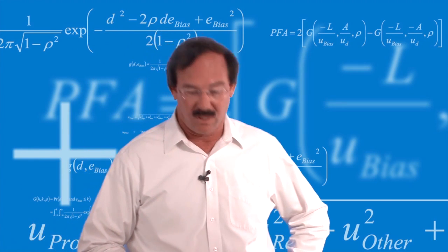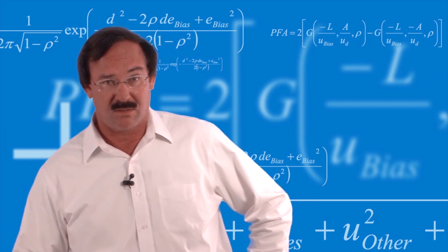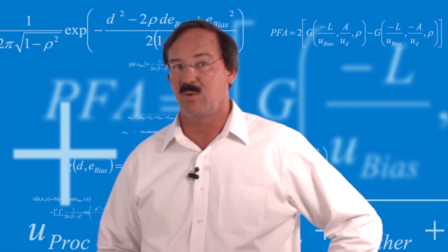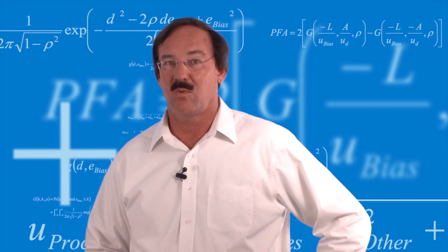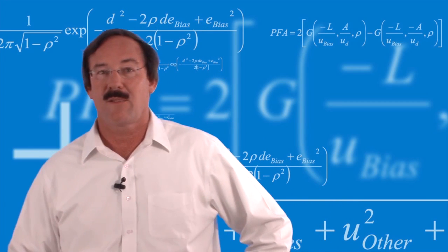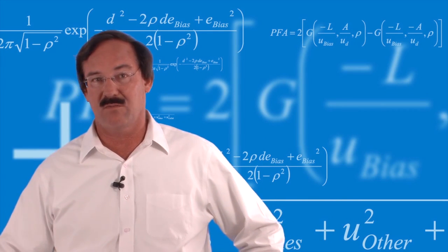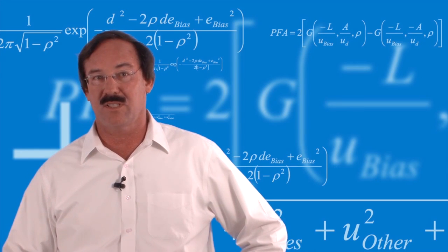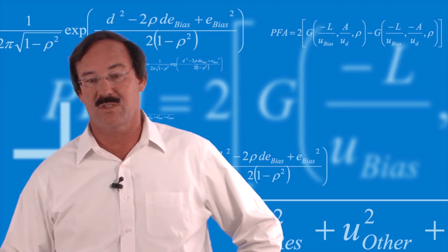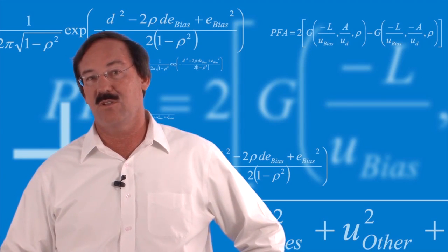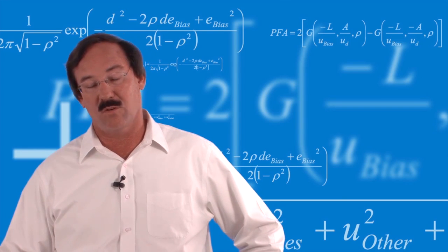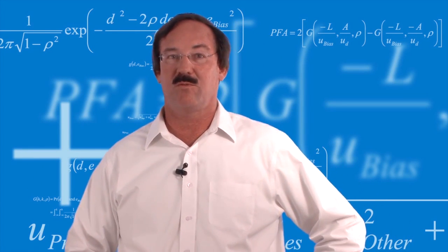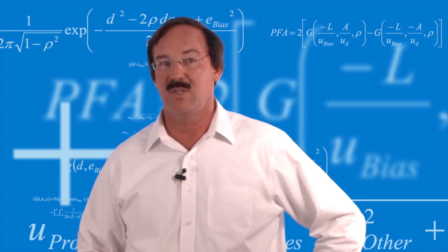I want to make one other note here, and that is, in my experience, whether or not calibration labs provide you with an actual measurement report, I've yet to see any time where they don't provide a trace report. Said in a positive way, every calibration lab that I've ever seen provides a cal certificate that has a list of the instruments that were used. And that's really another way that you can do an audit, because if you think back to our first module, we said, think about which specifications are key. That can tell you which performance tests should have been tested.